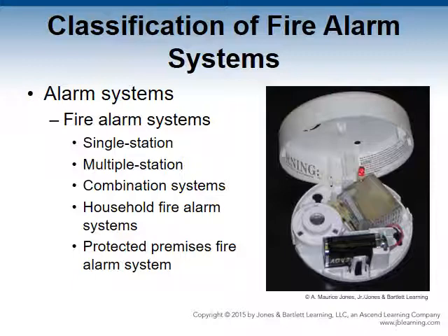Protected premises fire alarm systems are typically found in commercial and industrial buildings. They provide audio and visual notifications within the property they are protecting. They alert occupants of a fire emergency. They notify occupants or staff of system trouble and supervisory conditions. They may be a single manual fire alarm box and bell system. Some interface with other fire protection, building, and life safety systems. Some, but not all, have communication capabilities that report to an on or off-site location to initiate the appropriate response.